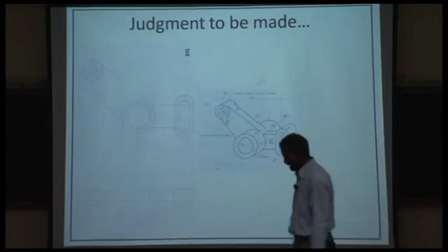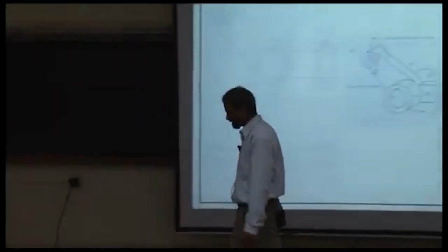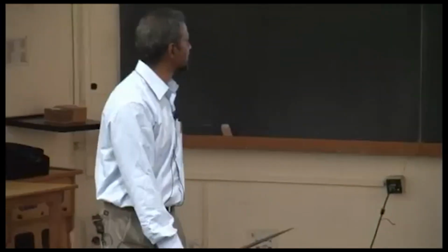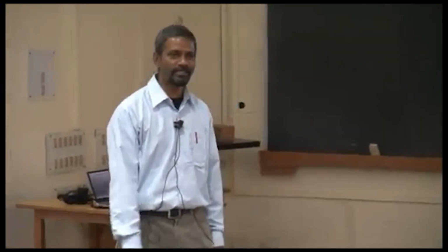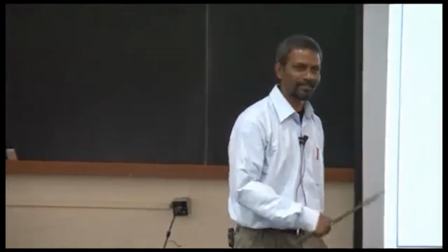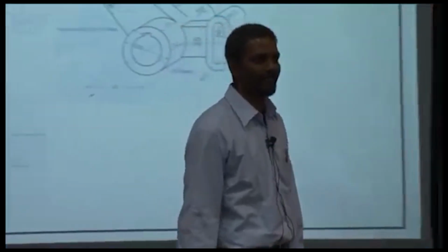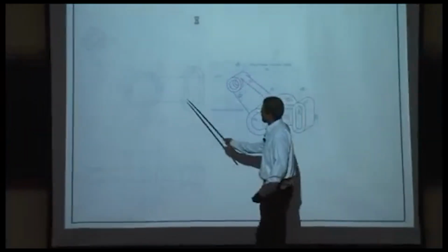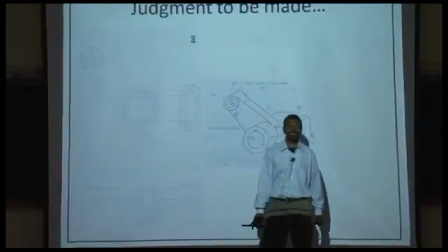We sat and discussed this, and one of my colleagues said, this doesn't seem right, because they happen to be a part of the main machine part, so they need to be sectioned. So the entire thing gets sectioned, and there's no point asking you guys to work on this question, because you're going to be drawing the outer profile in the front view and sectioning everything. The entire thing is going to be hashed. I agreed with him. These guys need to be sectioned.